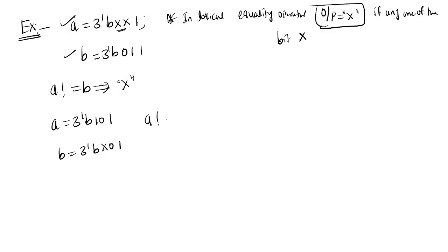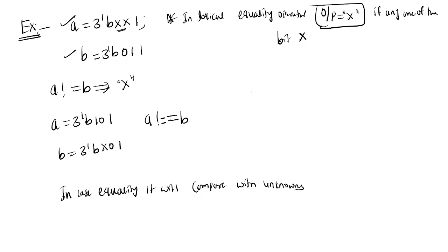A case not equal to B. Here in case equality, it will compare with the don't care also. In case equality, it will compare with unknowns also.